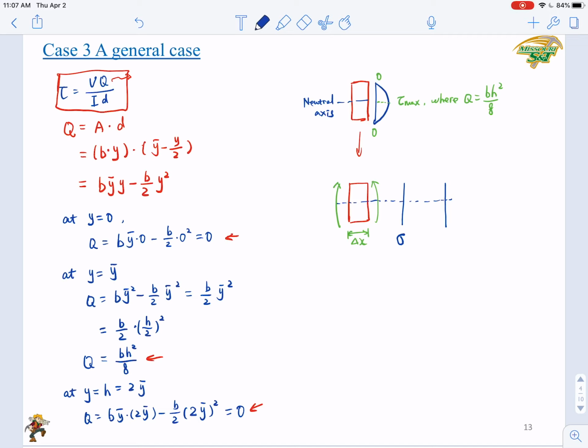If this is the bending moment, according to the bending moment shown here, the part above the neutral axis will be subjected to compression, and below it will be subjected to tension. Right, so the distribution will be maximum value on the top, compression, maximum value of tension on the bottom. So the distribution will be like this. Right, here we assume the linear distribution.